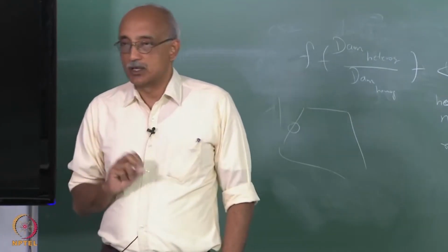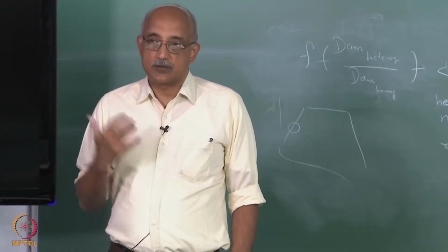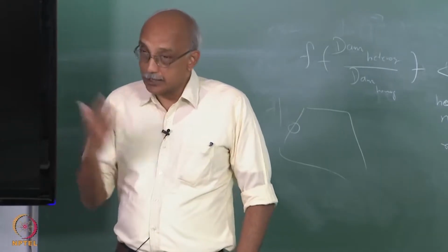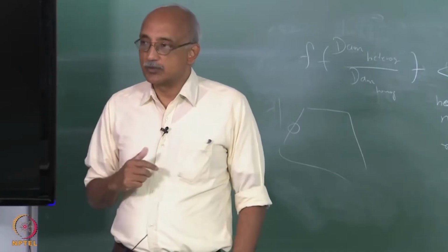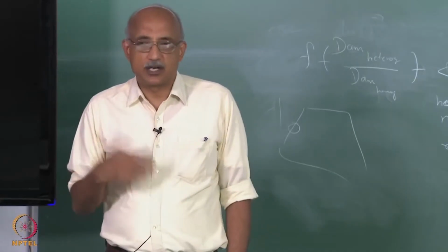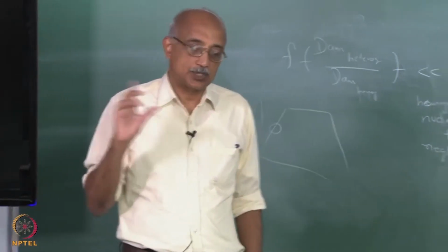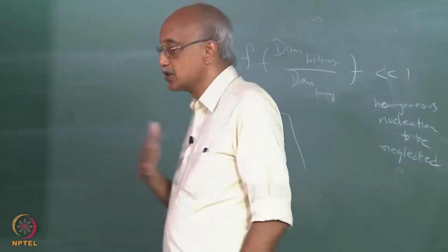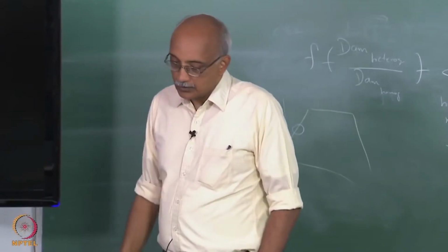there is actually two of them. One is thermophoresis, and in order to defeat thermophoresis, you have to keep the reactor wall temperatures high to make sure that the driving force for thermophoresis is kept as low as possible. The driving force is the temperature gradient. So, the smaller the temperature gradient between the substrate and the reactor walls, the less the propensity for aerosol particles to be directed towards the wall for deposition. So, that is the first thing.